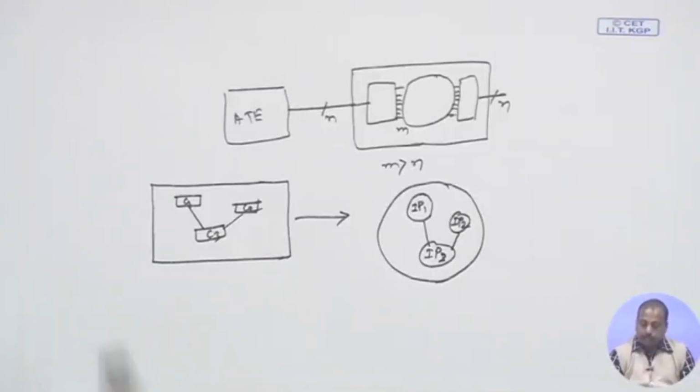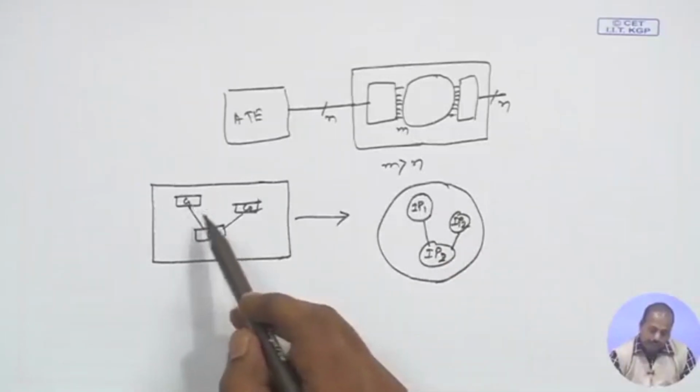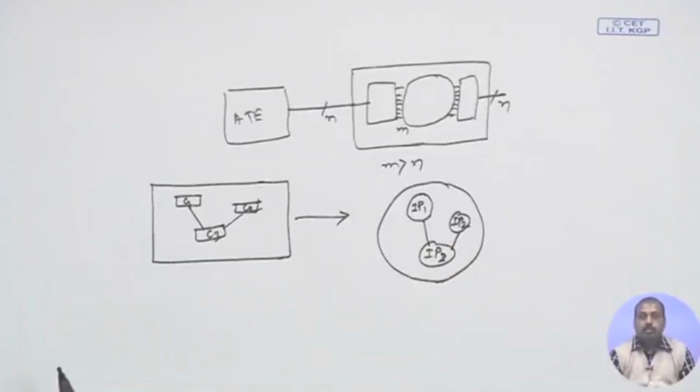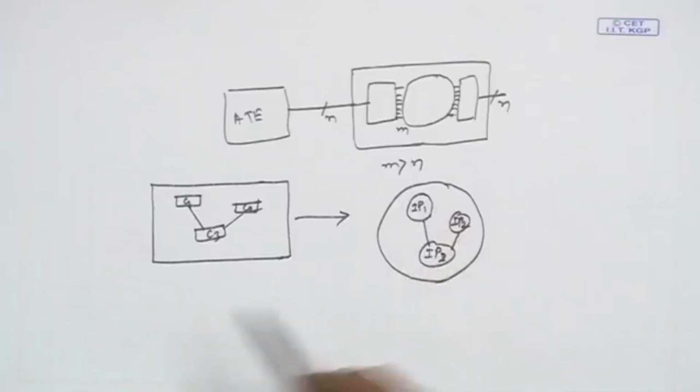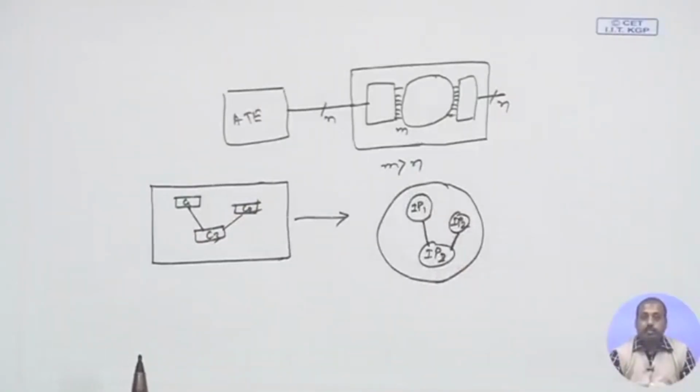So, the advantage that we get is that the off chip communication that we had from C1 to C3 or C2 to C3 is getting translated into on chip communication. So, they are going at the same rate as the original one. The rate at which these individual IP cores can operate, these channels can also transfer data. So, these signal lines can transfer data at the same rate, and the delay is much reduced compared to the off chip connection.